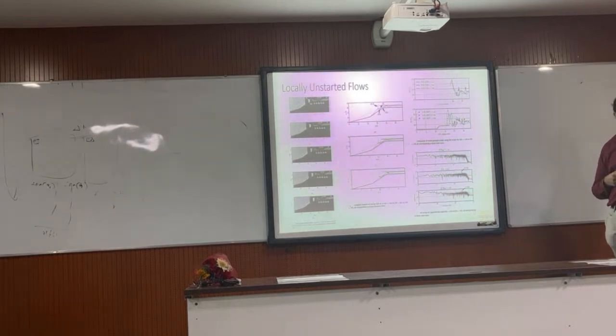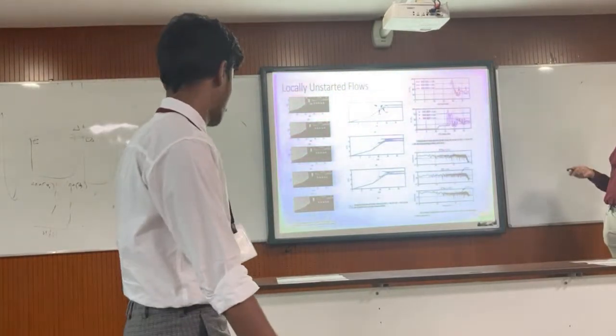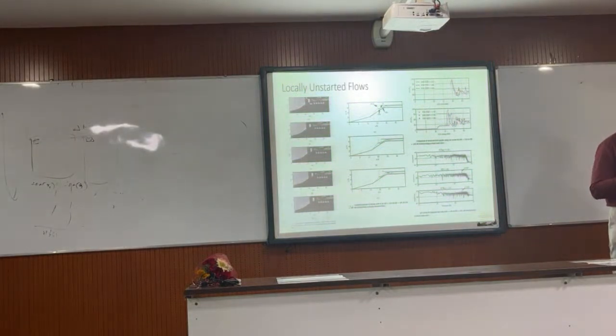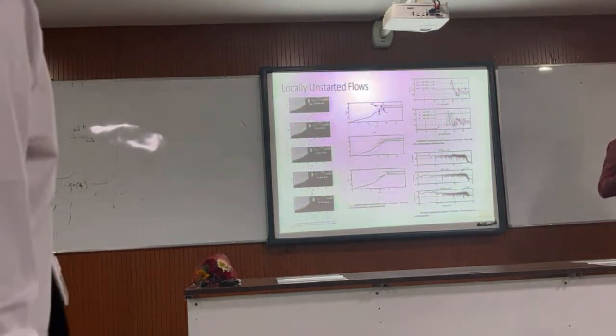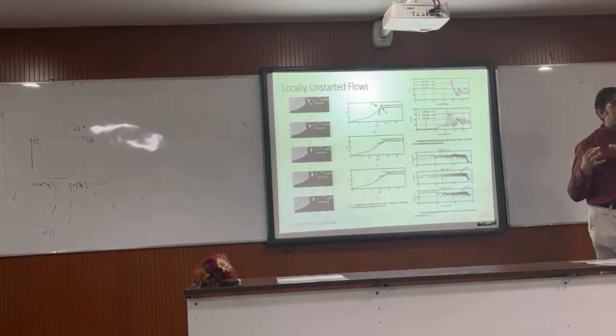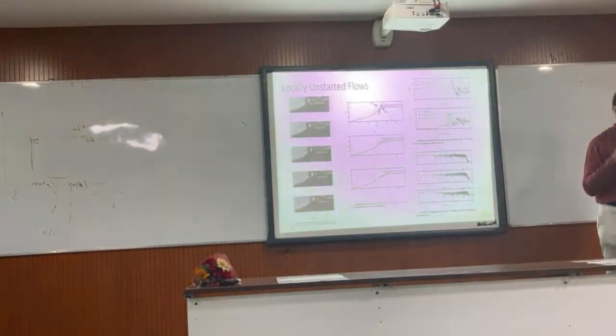This is mainly for hypersonic flows, where pressures compare well. As I was telling you, we haven't done high enthalpy. With high enthalpy hypersonic flow, you would not have constant gamma. This is high Mach number, but enthalpy is not very high. Therefore, we can continue.